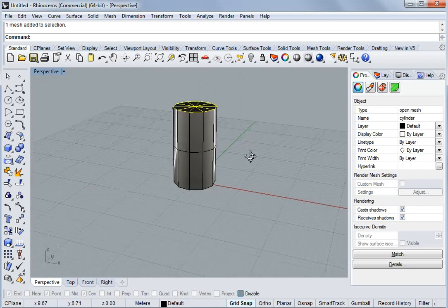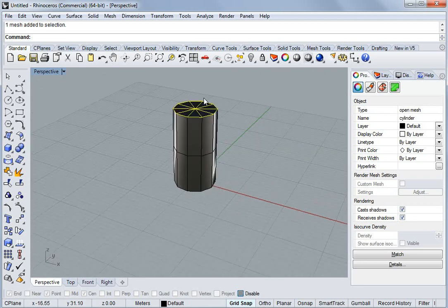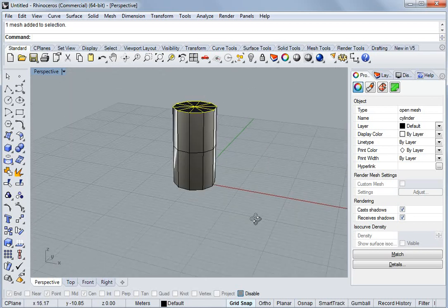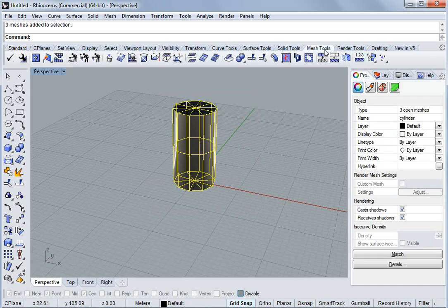They all have the same name of cylinder because they are all part of that one object, but the top and bottom have named groups associated with them. You could also name the outside edge, but it's not required. FlexPDE will give it a default name that you could use later if you wanted to, but most important is if you want to apply a boundary condition, it's nice to have a convenient name.